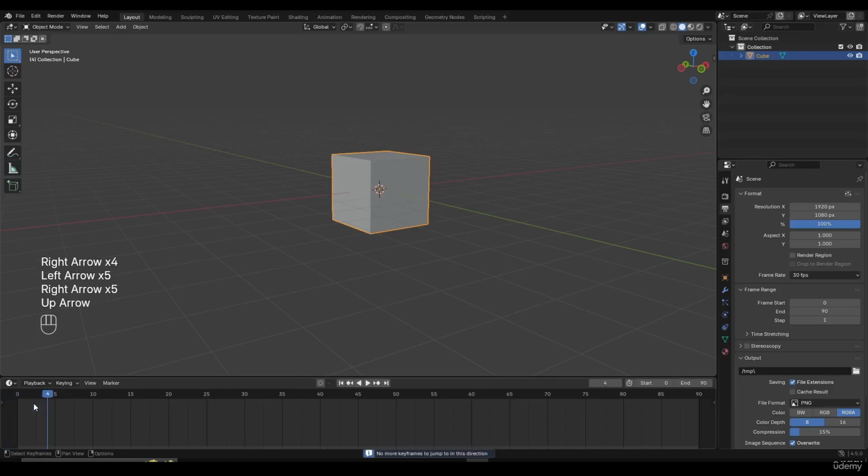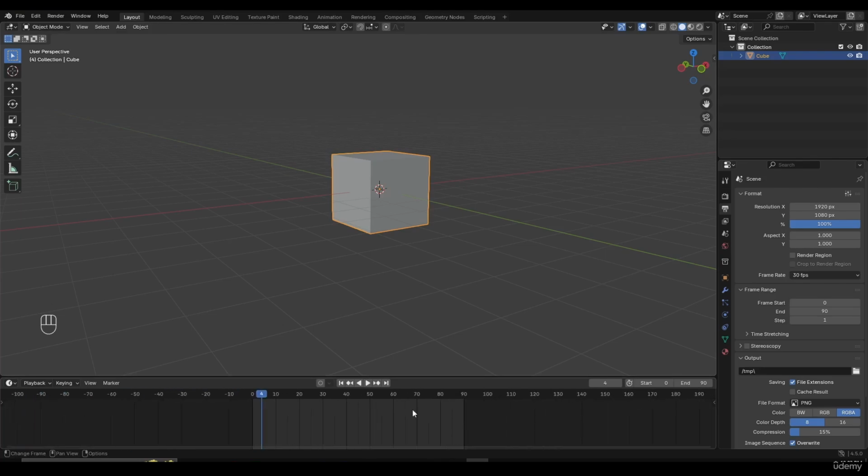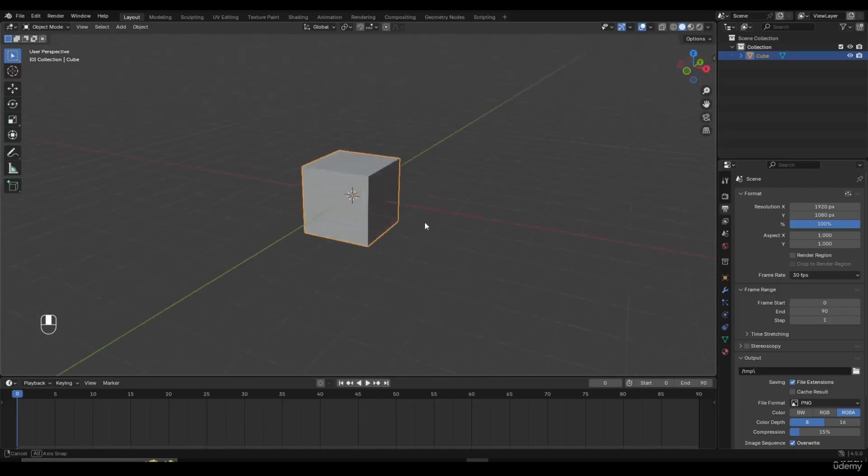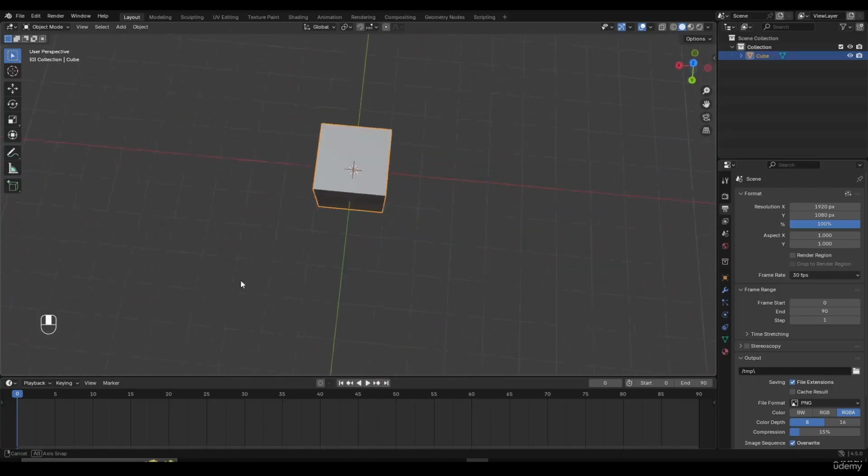You can also use the up arrow and down arrow, but for that you need to have keyframes set. And we're going to learn about keyframes later, so don't worry about that. So now we've learned how to move this, so we can zoom in and out, move it side by side, home, set the end frame, set the start frame, set the current keyframe, which is this cursor. So now I think you're ready to jump into your first animation. If you haven't done animation before, then you can follow along and make your first animation.